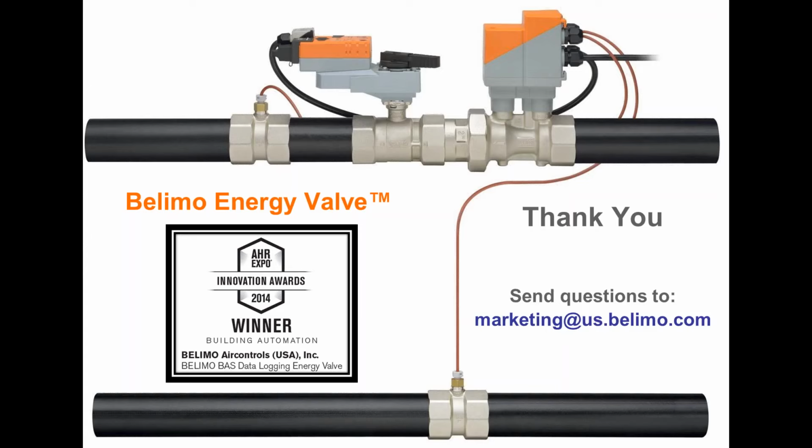Yeah, yep. Okay, perfect. So the first question we have is from California. How do we get feedback for our California Title 24 to reduce speed on the pumps just to satisfy the worst case load? Gotcha. So California Title 24 requires that the differential, actually, I think it's a static set point in California, but the pressure sensor that drives your VFD has to be reset based on the position of your control valves.